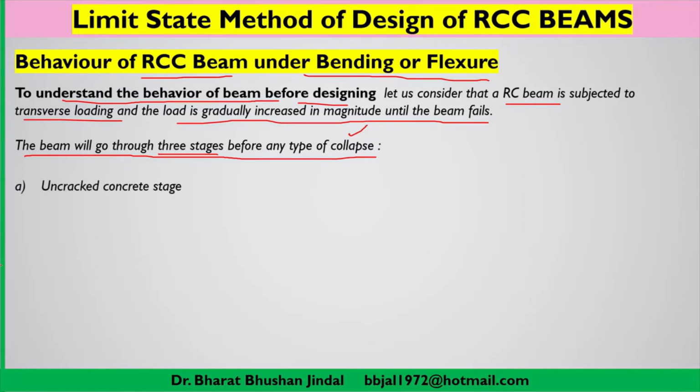Very first is the uncracked concrete stage. You have to keep in mind that concrete is prone to cracks, or concrete may have some porosity. So when we take any RCC beam section subjected to loading, it will go through 3 stages before finally collapsing.